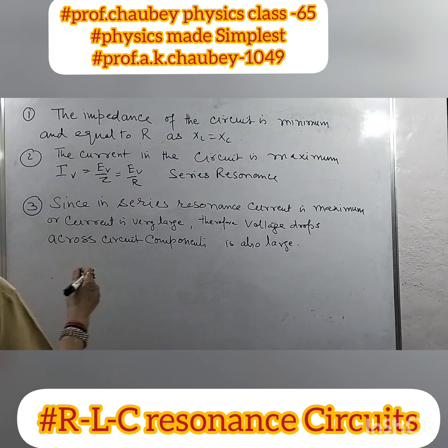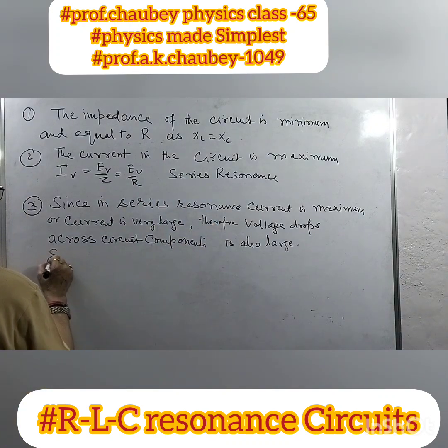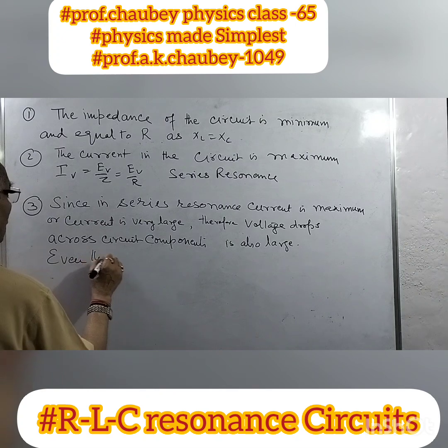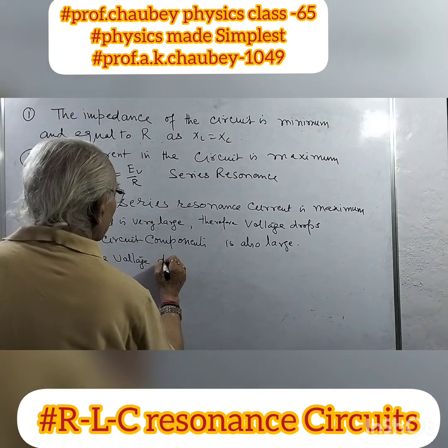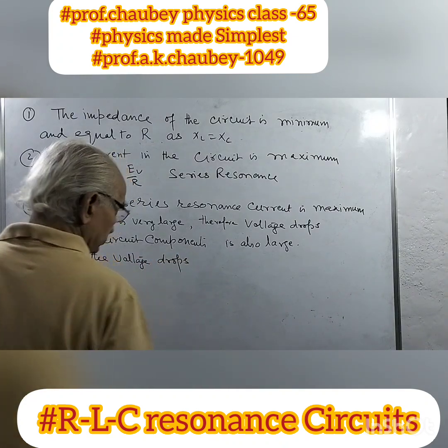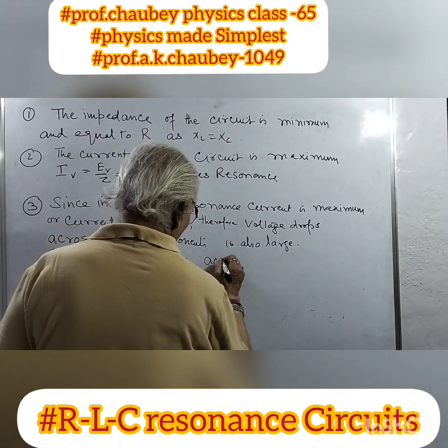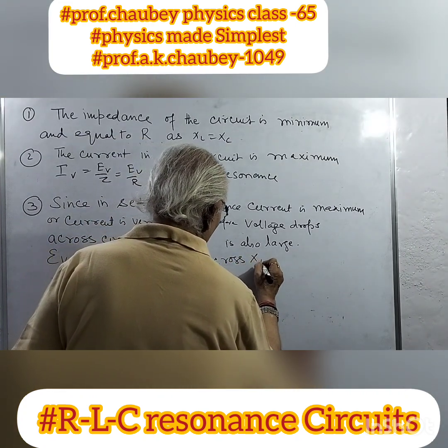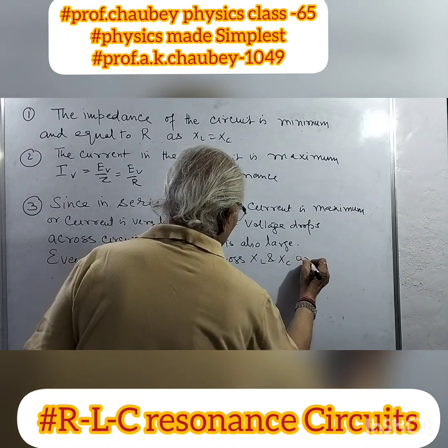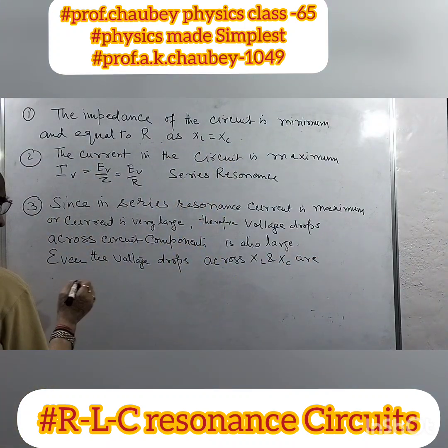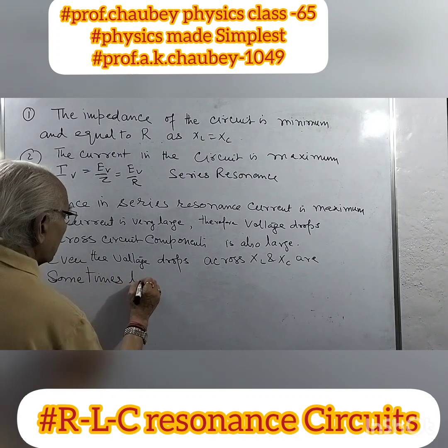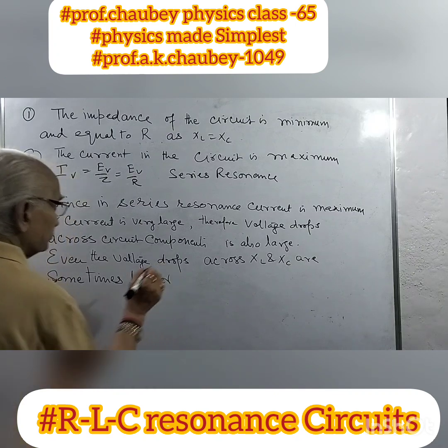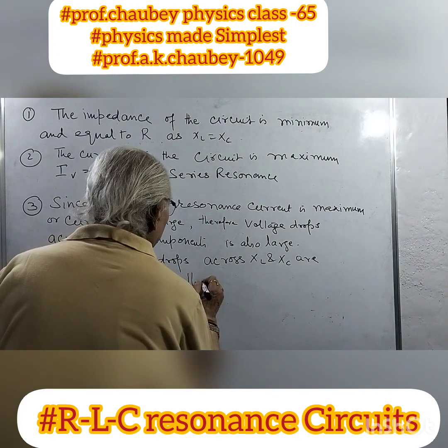Sometimes, because current is very large, even the voltage drops across XL and XC are sometimes larger than the voltage applied.